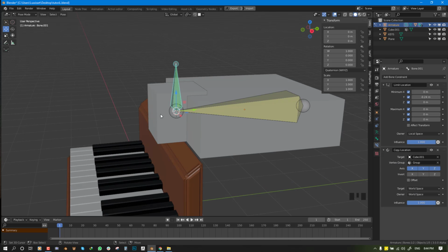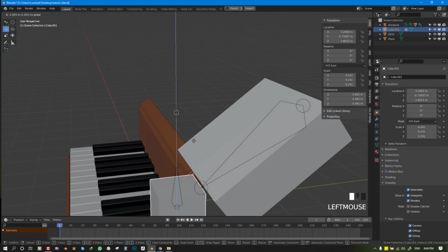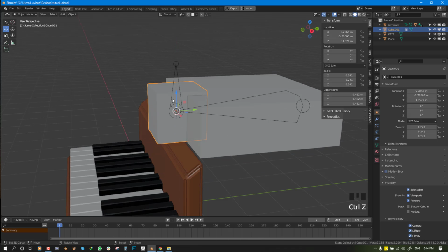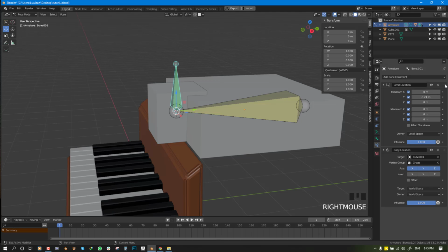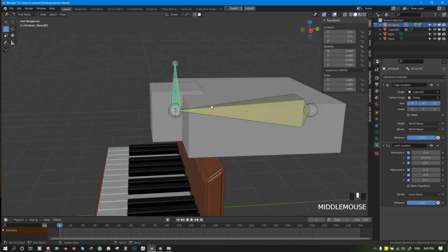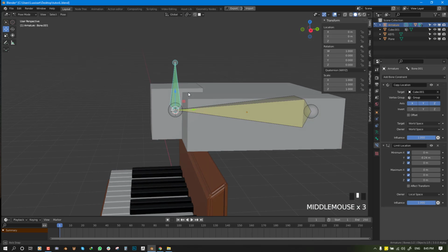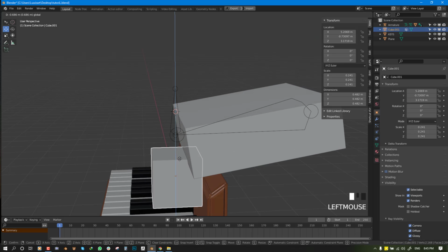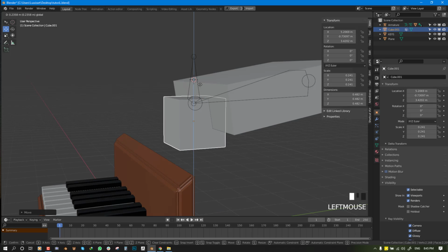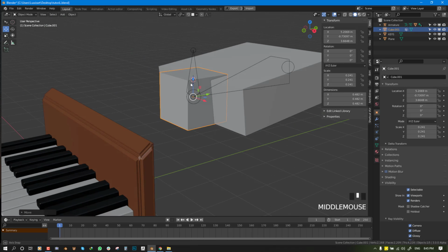Another thing is currently if we move this cube downwards, we can see it overextends the constraint we've put for it. So we needed to respect that particular constraint we set up. And the way to do that is basically switching the hierarchy. So Blender constraints, like modifiers, work in hierarchy. The one that's first is being respected by the one at the bottom, so everything works together with each other. So now if we move this, we can see that the key stops at a certain extent and cannot extend beyond that, and it cannot go in any other direction than downwards.